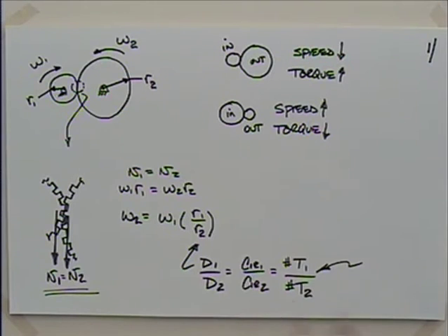Now, for lighter duty, more modern transmissions, they put synchro meshes in them so that you're actually not shifting the gears. The gears are actually running all the time. That way you can have a little better gear cut, and we'll see this in the transmissions. It can be a little quieter and things like that. And shifting the synchro meshes is quite a bit easier than trying to shift the gears. But it still becomes a velocity game. If you've ever tried to limp home without a clutch, you can actually shift pretty well without a clutch, but you have to get the gear speeds to work out.